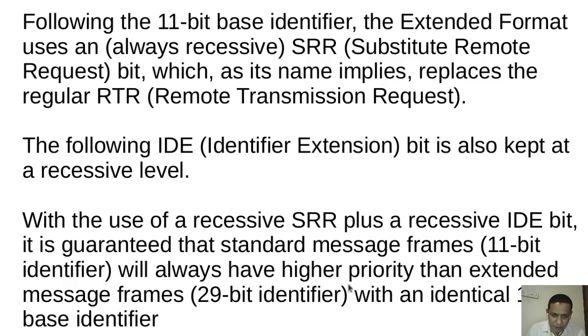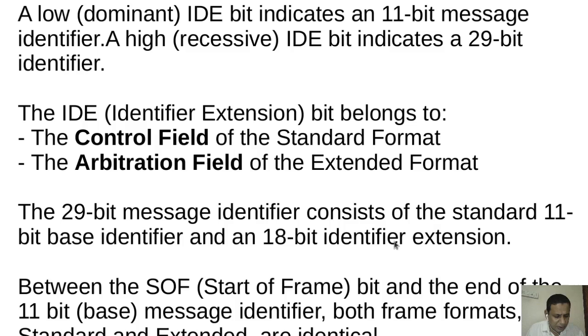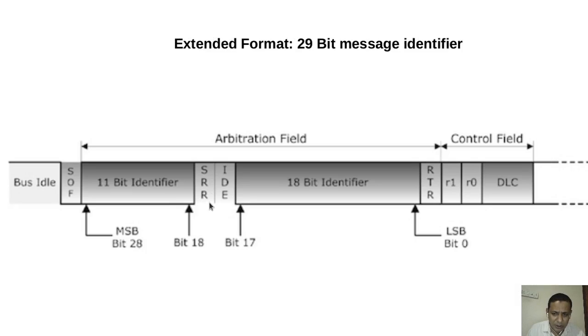That is decided by the value of the SRR bit and the value of the IDE bit, and the standard frame format will dominate.